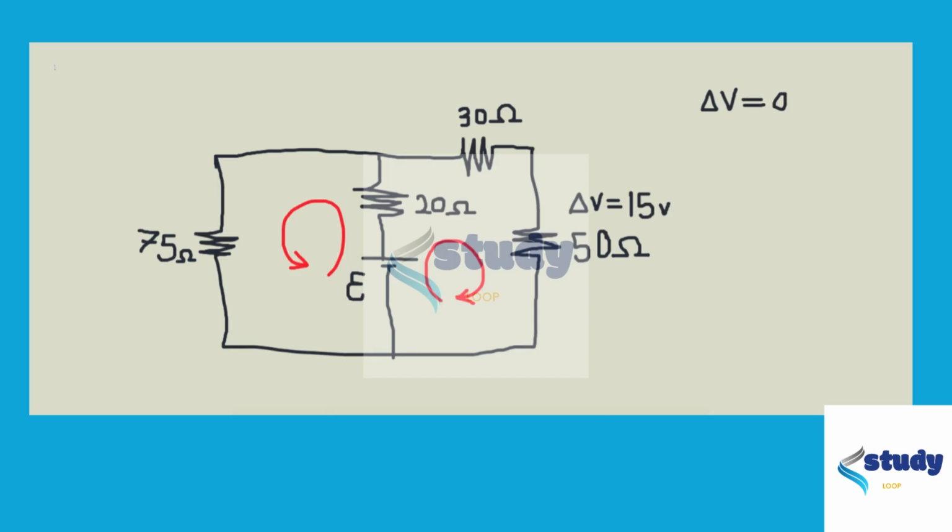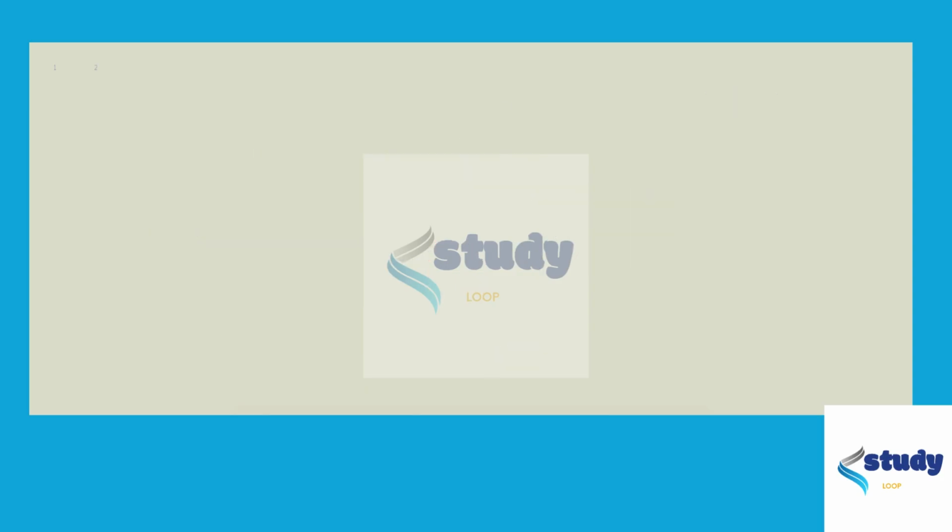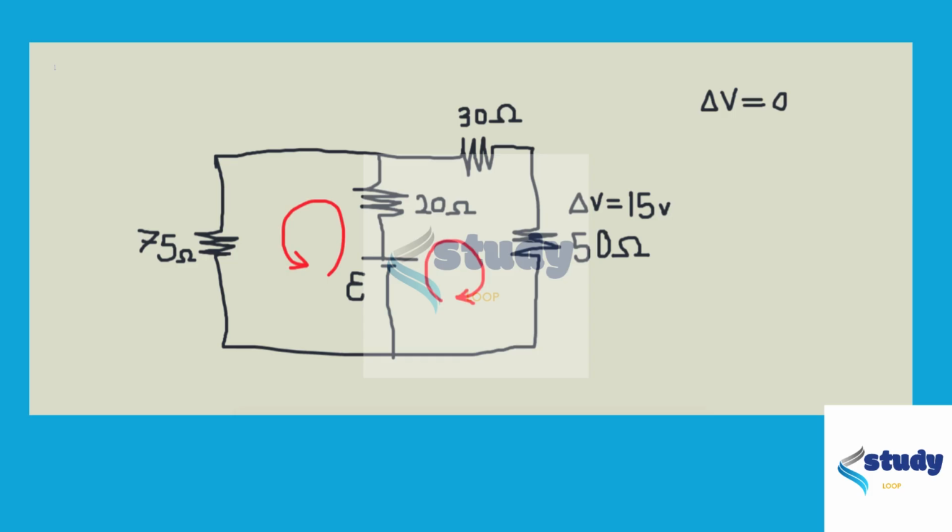Now, change of potentials include the potential drops due to everything in this circuit. So this includes the battery as well as all the resistors. So let's specifically talk about the right-hand side loop. Okay, so the battery here is going to raise the potential, and then it's going to drop across all the resistors. So the signs on the resistors are going to be opposite that of the battery, and that's how they're going to equal zero.